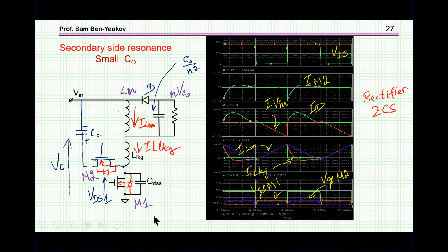This controller for the active clamp flyback will include whatever is necessary to turn on these transistors, and also to have adaptive control in order to switch at the right time so as not to build extra circulating current. Also, I should mention that of course when the power goes very low, you have to go into burst mode, and the controller usually will take care of this also.